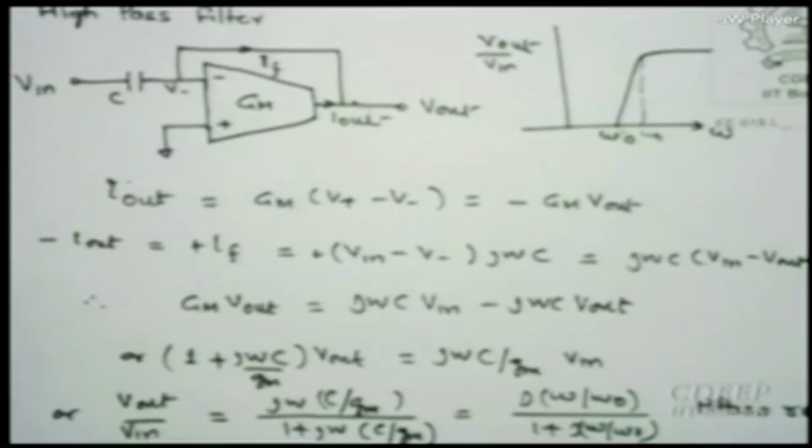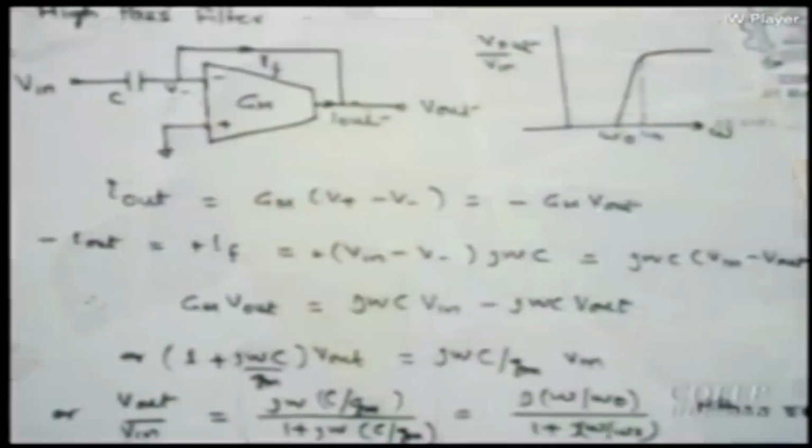Is that okay? So now I got two circuits. This is a high pass filter with a capacitance here. A low pass filter, where was the capacitance? At the output. Oh, so now I got a trick. I have a low pass and I have a high pass, and if I properly make the two combinations, I can make a band pass or band reject, depending on the cutoffs.